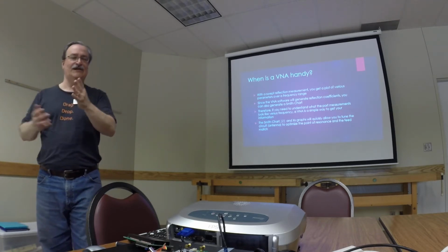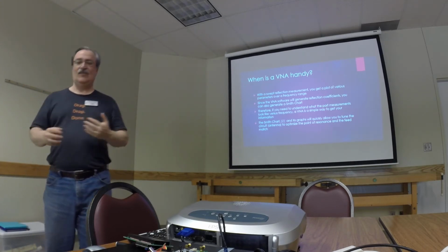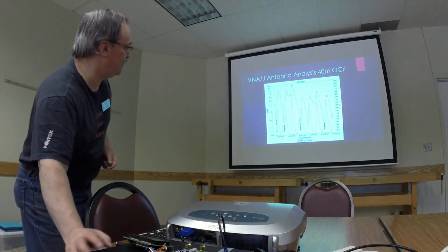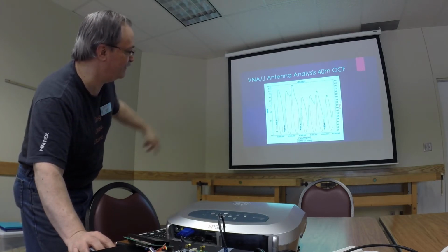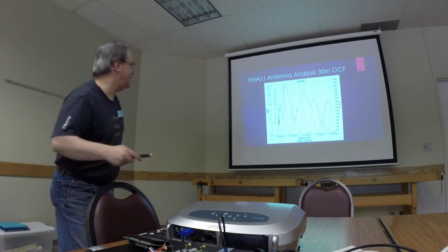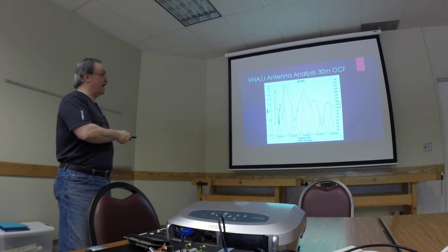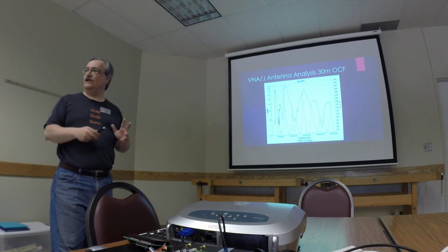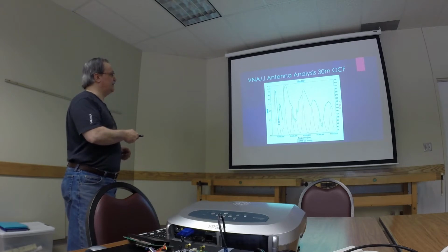Okay, so I'm giving you kind of the punchline here. So my 4-to-1 balun was turning my impedance as seen. There's the 40-meter OCF and all the points from 7 to 50 megahertz. And there's where I started, at about 1.8 to 1, direct, no tuner, and that was an objective I had, not to use a tuner. I wanted to get to a very close feed impedance that was accessible.